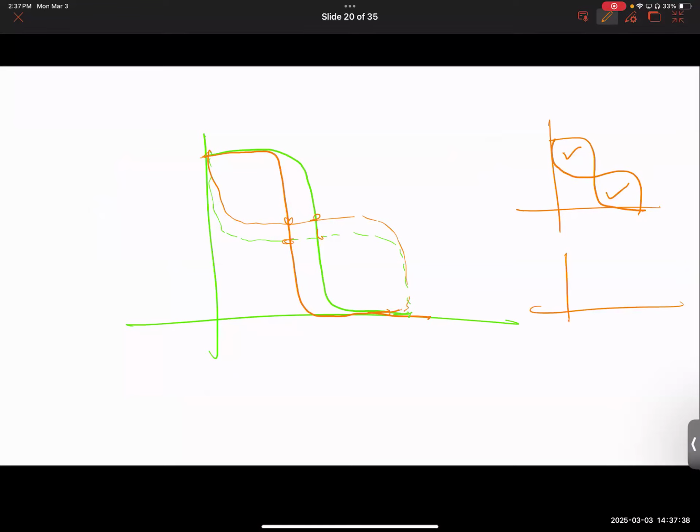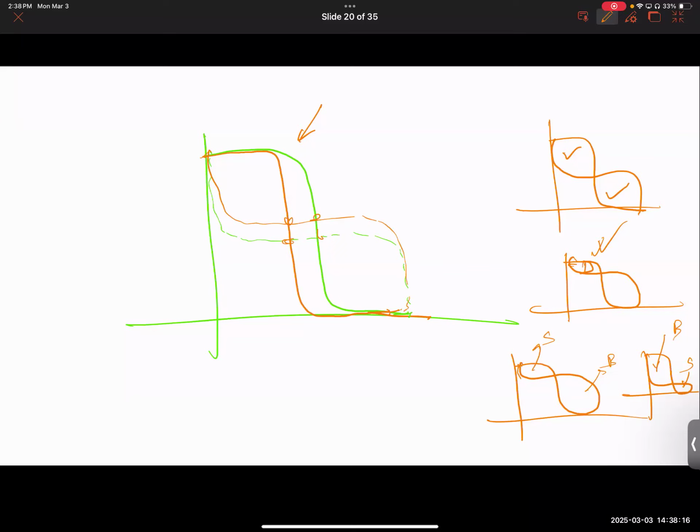Okay, and remember, if one of these lobes becomes small and the other one becomes big, does that help you? No, because the smaller one will become the bottleneck now. Remember, we talked about SNMs, and whichever is the smaller one tells you what the SNM is, not the bigger one. So it doesn't make any difference. But apparently, for NCFET-based SRAM, it's possible to create lobes like this: small, big, big, small, big, small. I'm giving you the big picture here.